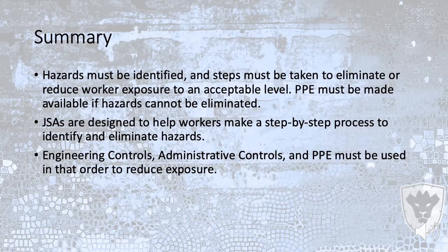A summary, really wrapping this up for everybody. Thank you very much for your patience and bearing with us this month. A lot of information. Hazards, first of all, must be identified. And that's just a process of taking your time, slowing down, developing a safety language and culture with your crew, talking about what could go wrong, especially if you're working on workover rigs, especially if you're working on drilling rigs. If you're walking into SIMOPS situations where there's work going on that you don't understand, but you're still exposed to the hazards, spend 5 minutes talking to the guys.